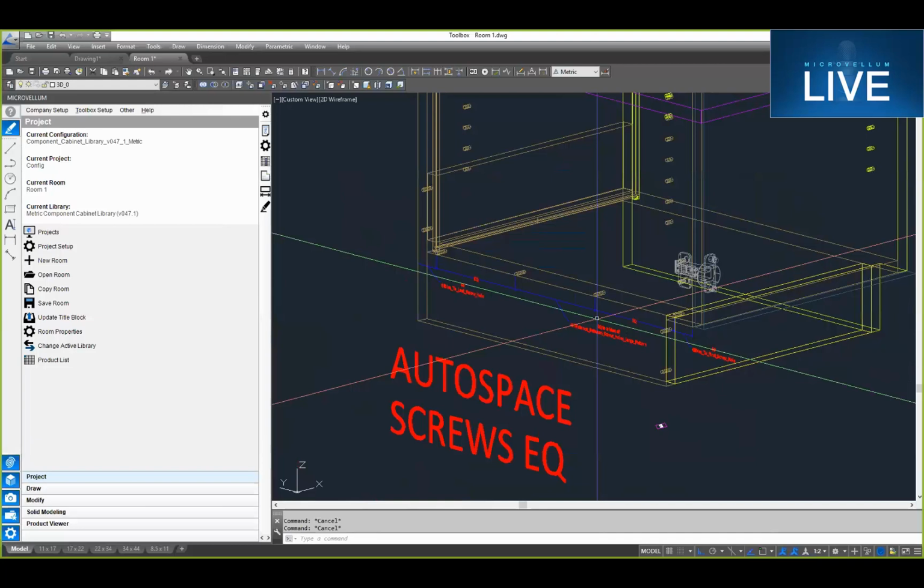A lot of companies will put the screws in anyway, but what we've seen is that by pre-drilling those, it really makes the assembly a whole lot faster, where your operator doesn't have to worry about what angle he's holding the drill at to put those screws in. By pre-drilling with either a 5mm or a 3mm drill bit, you're able to just quickly put a screw in there and hold the cabinet together while the glue sets up.